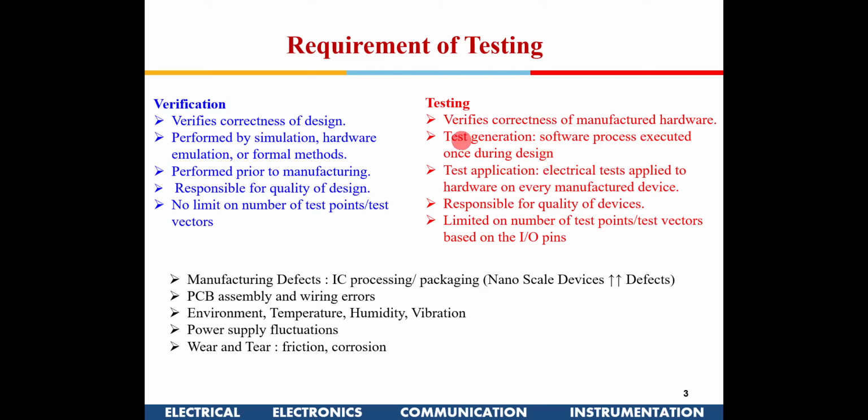Another thing is that during testing we are not going to verify, say for an adder, whether I am giving 2 and 2 as input and getting 4. That is not the purpose of testing. That has been done in verification, and we assume that if it is fabricated correctly, the chip will work. In testing we only see whether whatever has been designed has been properly fabricated. The focus is on whether during fabrication there has been a broken line somewhere, or a fault like stuck at 0 or stuck at 1 has been induced.